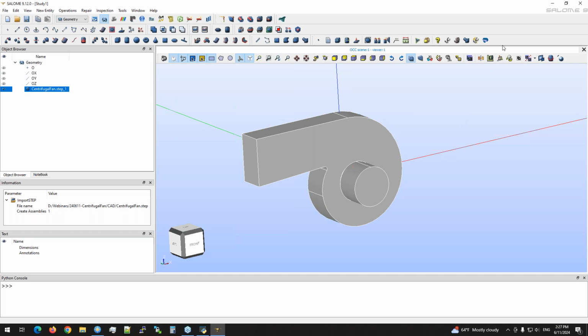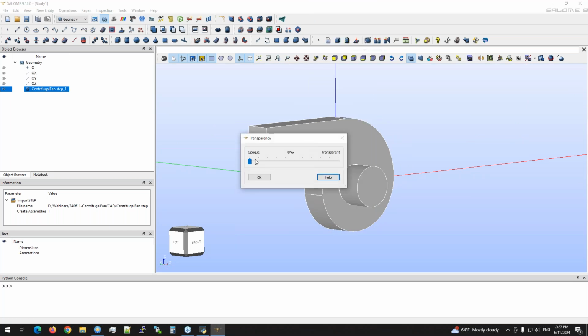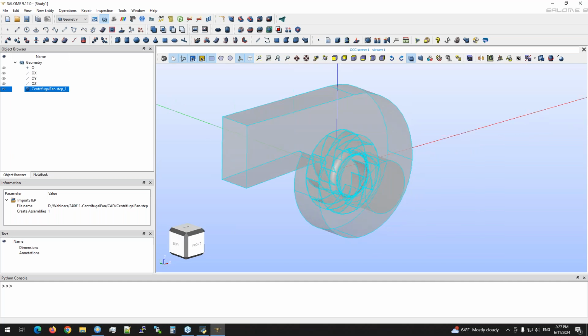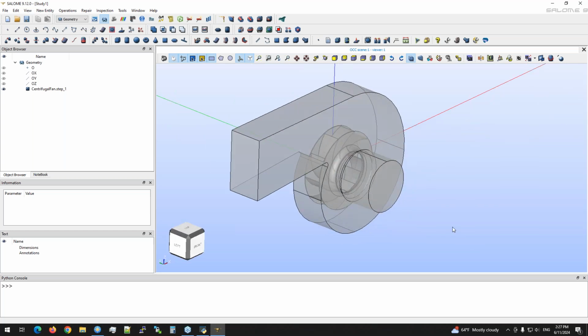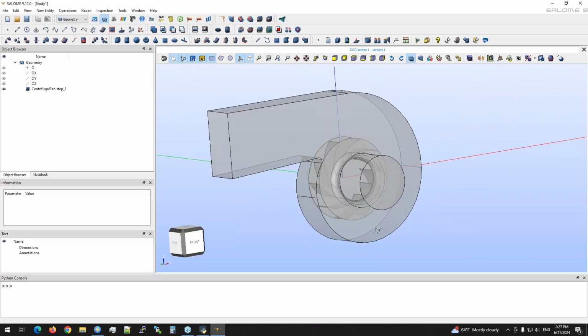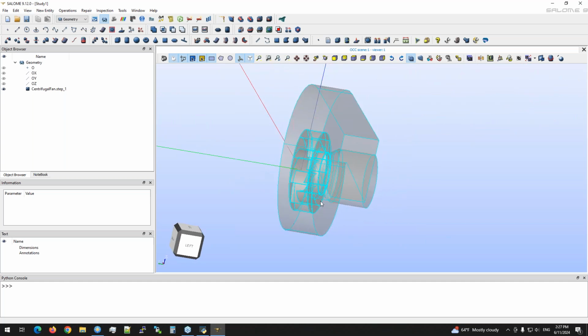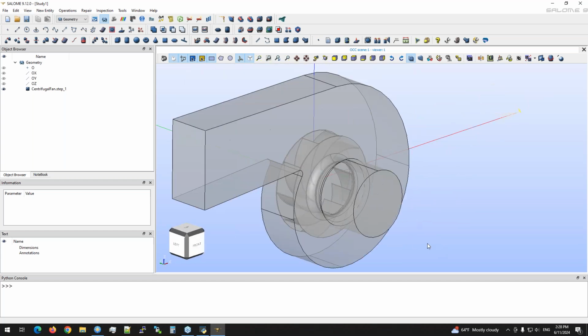So typically this you need to do in your complex model just to extract the flow part. And what is also another thing is to clean it and clear it from any unnecessary parts or very tiny shape which does not influence the overall efficiency or the targeted parameters you would like to follow. So the best results you always achieve with a nice clean geometry. So as you can see, the geometry includes all the parts we would like to model. It's a simplified geometry without any shaft geometries and all other details.